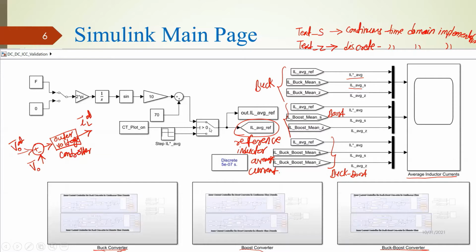We can only control the current, and then we generate this current reference. Okay, so this is a simplified way to check your current controller, but we will also see in an upcoming circuit diagram why I generate this reference like this. So here there is no voltage control implementation, we just have the current controller implementation. That is why we generate the reference inductor current like this.